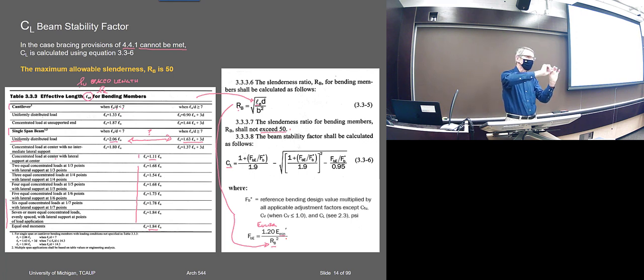It's not like steel, where you get this beautiful line that's the same for every piece you test. You're testing to get the E modulus, say. You're graphing the stress over the strain, and one will go like this, and the next one is slightly under it, and the next one in between, so they're not that consistent.